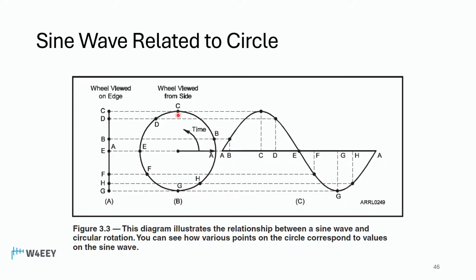Continues around, eventually it's going to get to its peak. It'll describe that dot, and then if you connect the dots through many more points to get the curve to look just right, it keeps going all the way around. So as we go all the way around here, we're tracing out a sine wave. There's two ways that we can look at this. One is, let's say that this is happening in 1 second. So this would be at 1/4 of a second. But what else is it? It's 90 degrees. So at A, we swing around 90 degrees. We can describe this point either in degrees or phase angle, or in time that it took to get there.